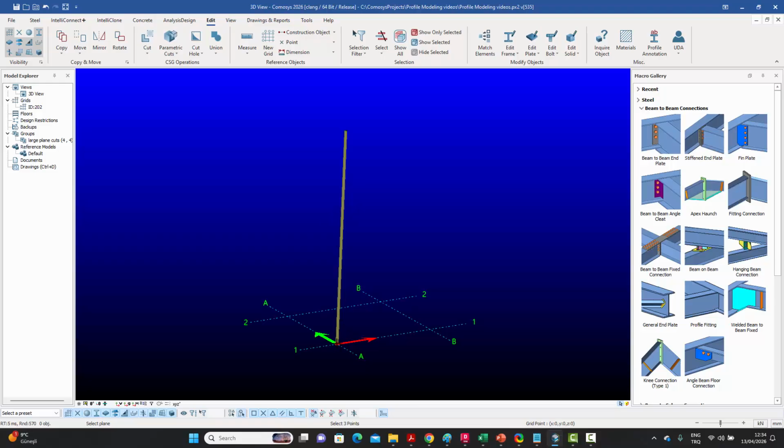So how do I do that? I can hover over this point and say DZ 6000, and then hover over this point and say DZ 6000, and hover over that point and say DZ 6000. And now that plane is defined, which is 6 meters above the base plane. And now it's asking me for the line, and as the line, I can show the start point over here and the end point over here, or I can turn on these nodes so that I'm sure what I'm clicking on. Now, when I do that, immediately a point will be created.